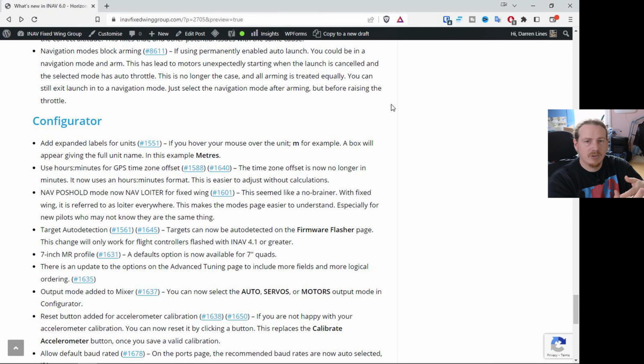But it gives that extra step so that you are actually specifically doing it. Loiter is a very good one, because when you throw it, it's going to stay in front of you and then start loitering. You can see where it is. Return to home comes back over your head, and you can't keep an eye on it. So loiter is a better option.